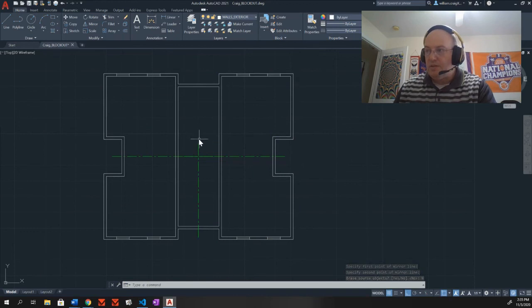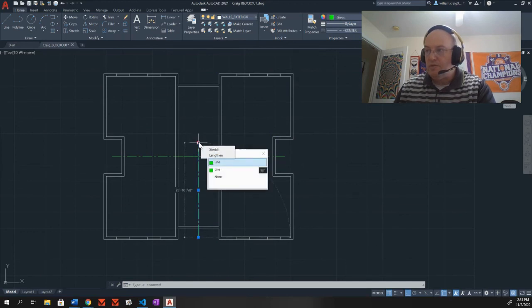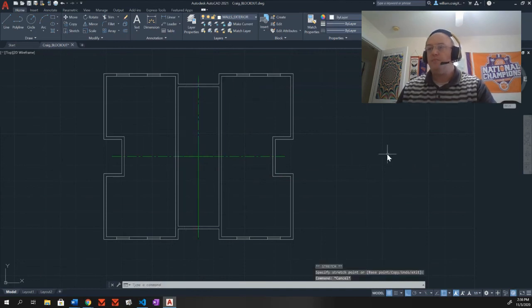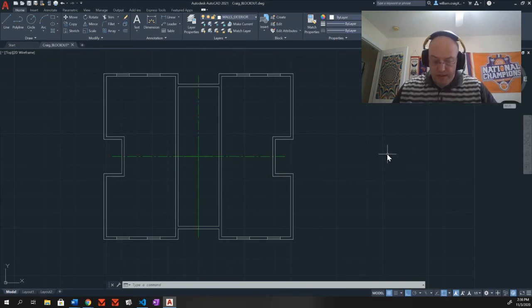Now I'm just going to take these center lines here. Center line. And extend it up. Perfect. And this is it. At this point, we have extend the center lines as shown using grips, which I just did. And we have it done.